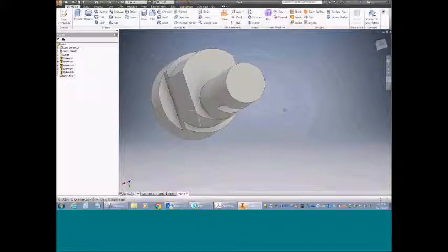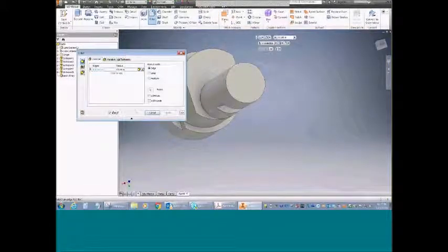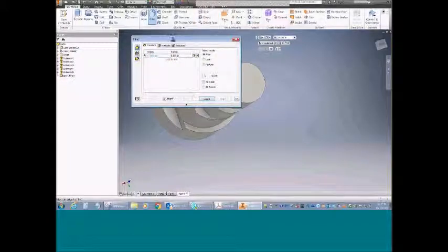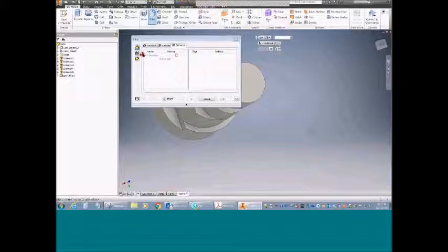Now there are some fillets in here, so I would go through this fillet command pretty in depth. I would talk about how we can select edges, loops, we can fillet an entire feature, we can set up different radiuses. We can do variable fillets where it starts out as one radius and ends as a different radius. We can set up setbacks to specify our distance.